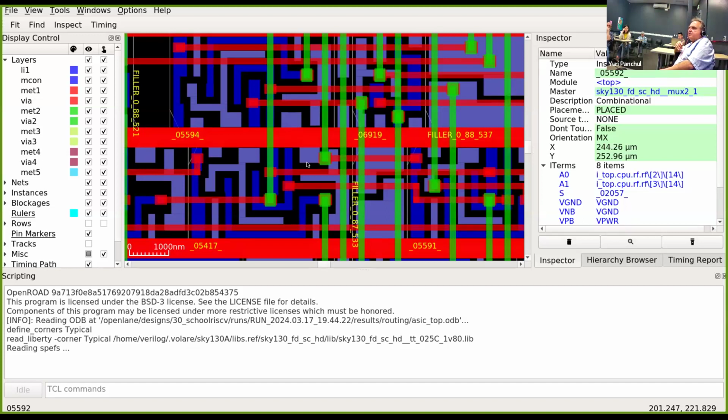They are buggy, but they use multiple layers of verification to make sure that if a bug does happen, they will catch it. They simulate on all the different levels, and then they produce a cheap prototype, and they do post-silicon debug. They put some extra registers which they can access even after they manufacture the chip.